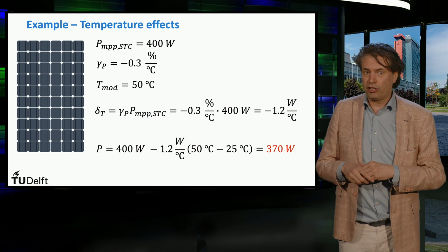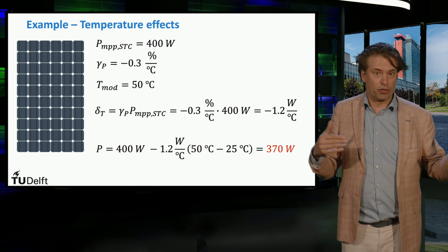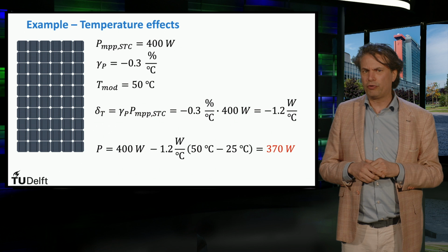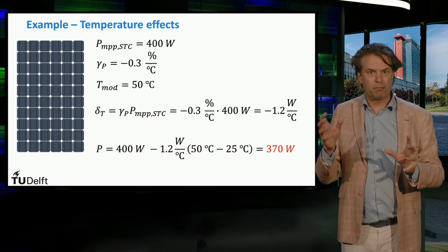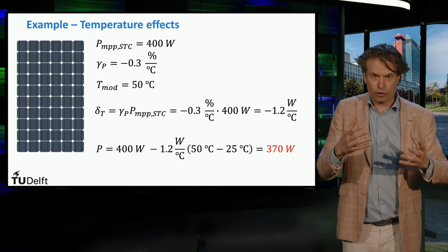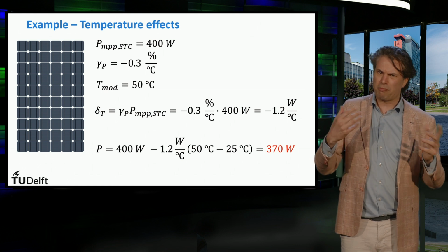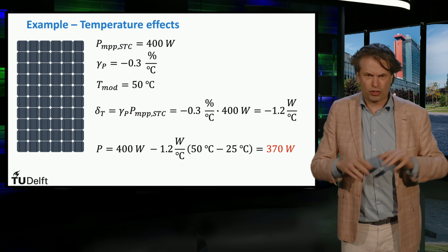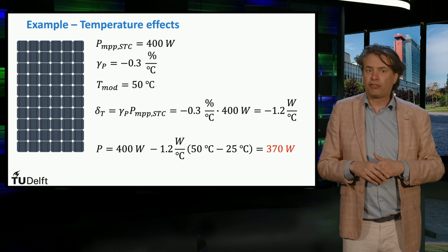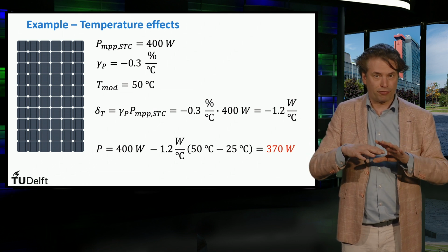Encapsulation of solar cells is a major factor in increasing the operating temperature of the PV module. The eventual operating temperature of a module will be a result of the thermal equilibrium between heat generated by the PV module itself and the heat lost to the surrounding environment. The heat exchange with the environment in turn could depend on several factors like the ambient temperature, the wind, heat transfer coefficient between module and the environment, and the thermal conductivity of the module's body.